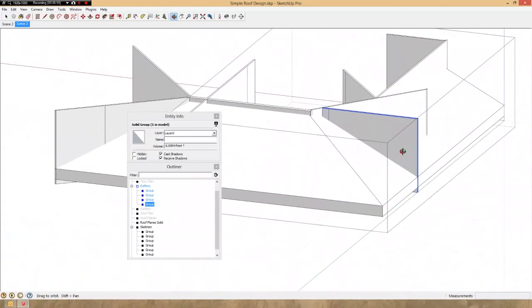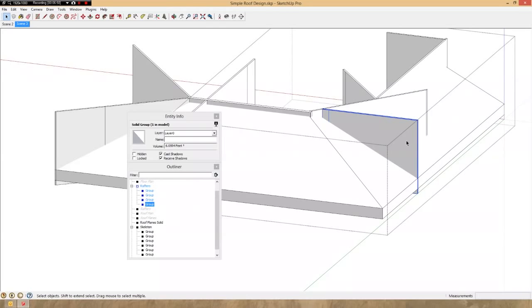I'm going to show you a method to do that that is kind of manual. There is a better way to do it. The way we're going to do it is with the tools that SketchUp provides you with the free version, SketchUp Make. If you decide to purchase SketchUp Pro, which is what I have, they have another set of tools along with many other features called the solid tools, and in them is a tool called the trim tool, which allows you to easily trim these things without having to go through the nosebleed that we're going to go through right now. But even though it's a bit of a nosebleed, it still works pretty well.